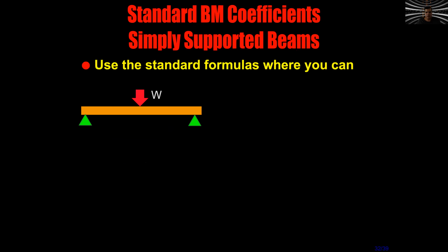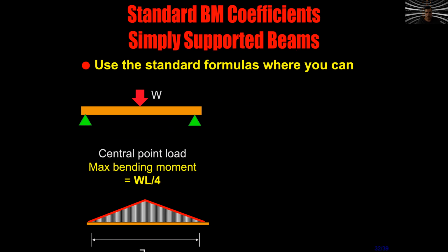Well, there are some formulas that we can use, and I imagine you studied in Structures 1 how to calculate the moment. For example, if we have a weight W in the middle of a beam, that weight has a specific value, imagine 100 pounds. Obviously the reactions will be 50 and 50 because it's in the middle, and there is a specific formula, WL divided by 4, to calculate that moment.